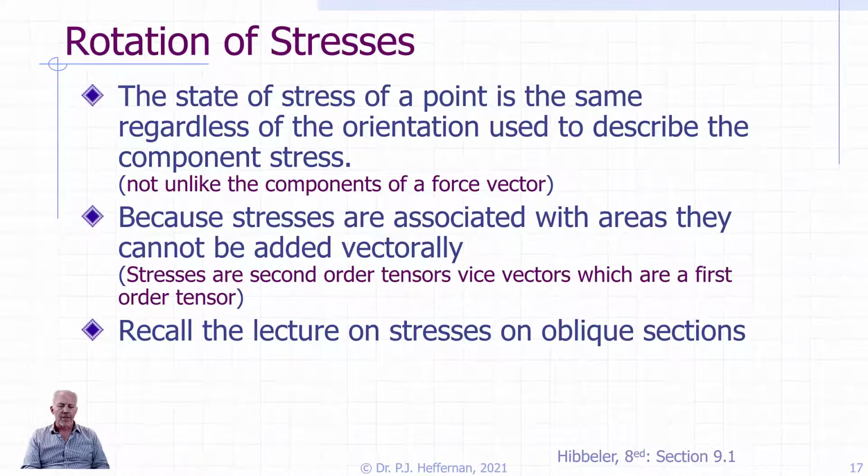that stress condition. So think of when we did forces, and say you have a force which is represented by a component in the x direction and a component in the y direction. Or let's say we gave you the x and the y direction and said, okay, figure out what force represents this. And so you would have to figure out some angle theta where the combination of the x and the y reflected the totality of that force. And it certainly would be in a worst case condition where the x and the y components collapse into that single force in the x direction only.